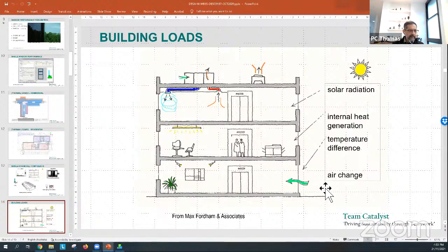And then finally, you need air. If you're in a building, you need to have ventilation so that pollutants are taken away and oxygen is replenished. But you also have uncontrolled ventilation. We spoke about infiltration: cracks around the windows and underneath the door, poor quality construction.